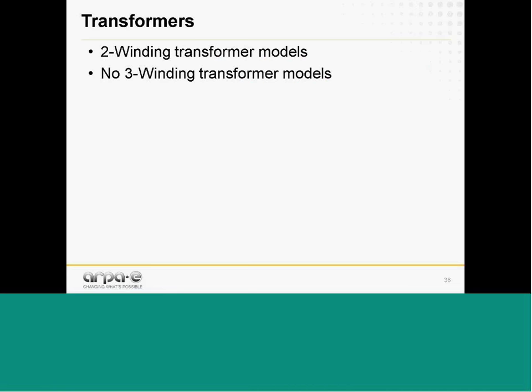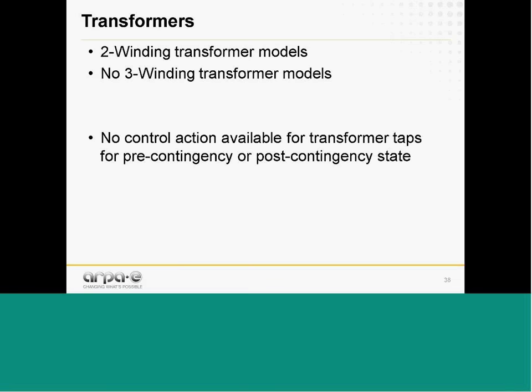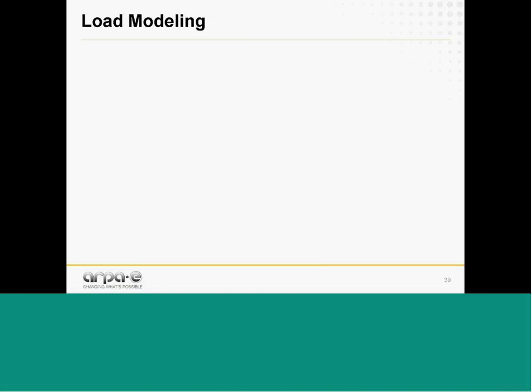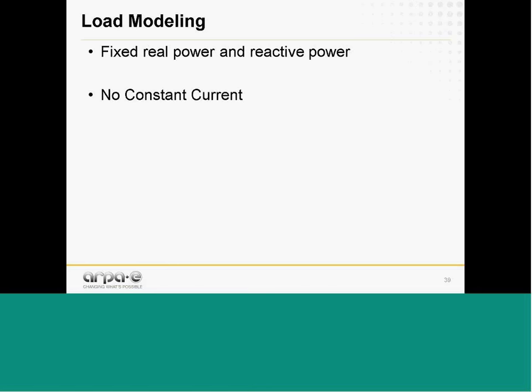Transformers, we have 2-winding transformers, no 3-winding transformers. There will be MVA ratings on the transformers, not amp ratings, okay? And at this time for challenge 1, we're not involving transformer tap adjustment, okay? Load modeling. We have fixed real power and reactive power loads. We do not have constant current loads. We do not have constant impedance loads. Some of these assumptions, I'll note, are likely to change for a future challenge. But for the first introductory challenge associated with the OPF, we're not getting into more of those issues.